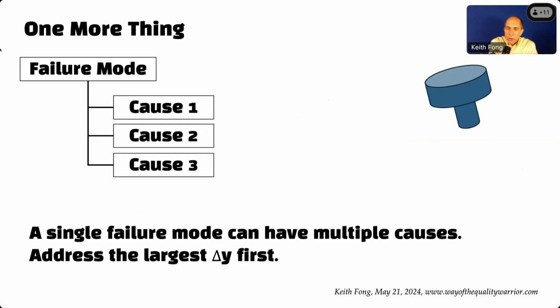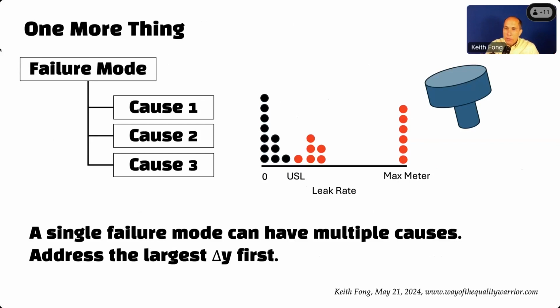As we did our investigation, we figured out that some of the parts that had been supplied, the shell was a stamped metal piece, and the supplier of the prototype parts had not set up their equipment right, and so there were cracks in that metal. If you didn't look for them, you didn't find them. But if you looked for them, you found them. When we found that, we continued our prototype part testing, and we were still failing some, but they were failing for much lower values.